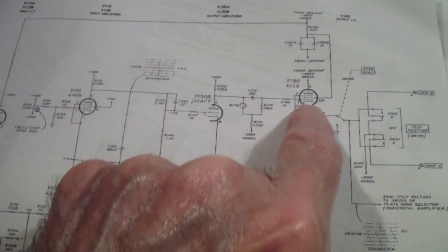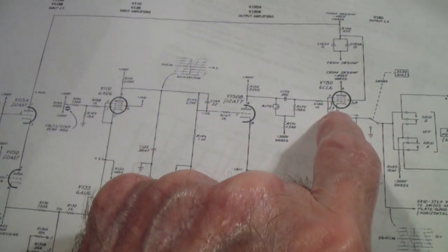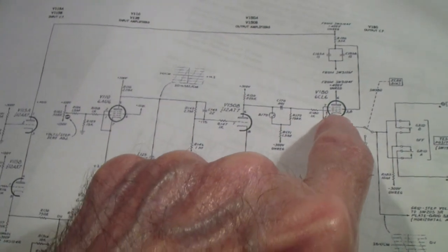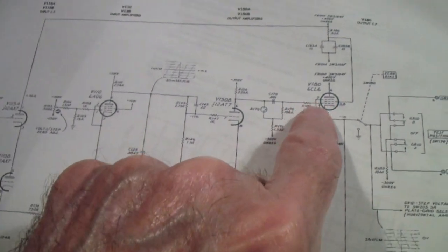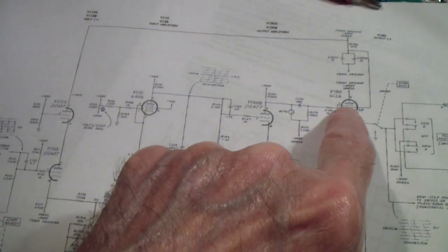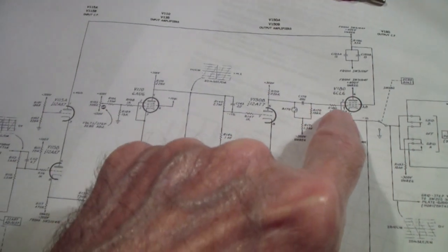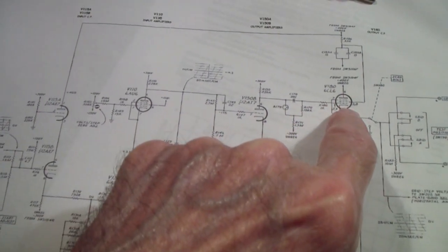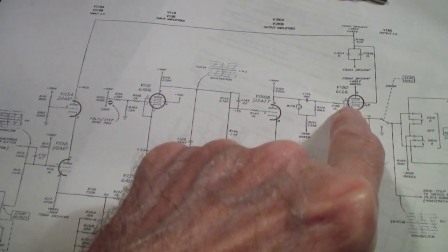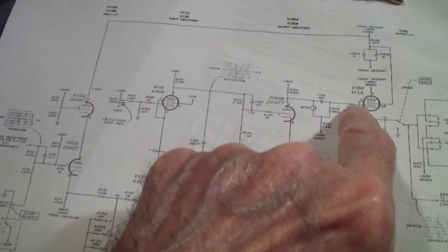By the way, I pulled it out and cleaned the pins of the tube again, and since then it hasn't happened, even if you wiggle the tube quite a bit. But I think what happened is, while I was changing the connections for another tube type, I managed to vibrate the scope just enough that the grid pin of this tube, which had oxidized a little bit, stopped making contact.